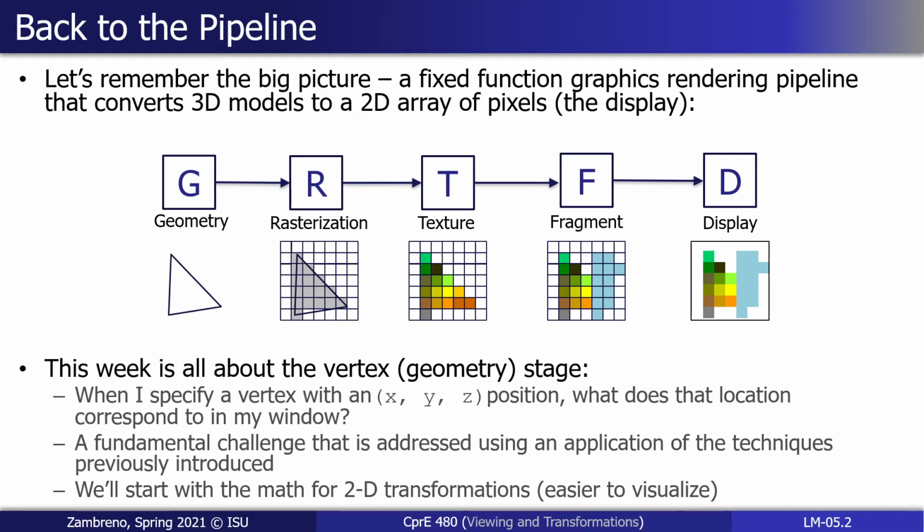Now, you may be saying, hold up, we already are doing that, right? We have a viewport module, this fixed function module that does that. That viewport module is doing the very final part of that, which is given an XY, in this case only XY, in the range -1 to 1, it figures out what fragment location on the screen that corresponds to. That's all that viewport is doing. In the more general case, for an arbitrary XY location in any range, or whatever range we could support in our fixed point hardware, determine where that should correspond to as then an input to the viewport module.